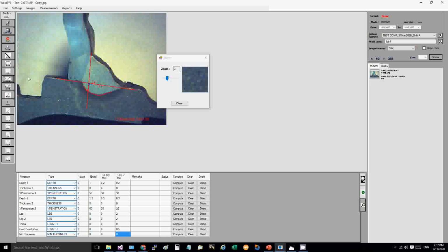Now the advantage with the curve is that I can always get the distance, the smallest or largest distance between the line and a curve. System will automatically scan this curve and find the deepest point so that I don't need to manually select the deepest point to get the penetration. I can optionally also define a point. We will do that option for the second penetration.